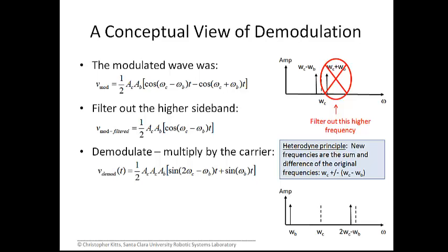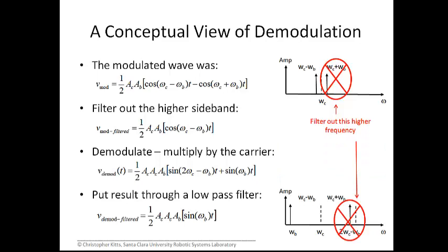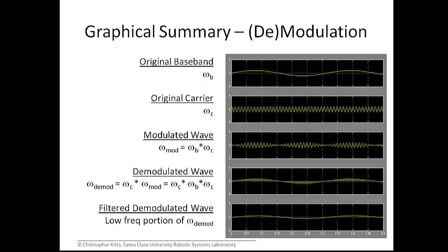If you remember, we're representing signals for spacecraft as time varying voltages, and the time variation is the frequency. That's the frequency content. So I've got that back by doing the demodulation process. And I simply filter out the high one because I don't need it. And so I'm left with the result, through a low pass filter, of a scaled version of my original wave. Okay, I get my original baseband back, but it's scaled.